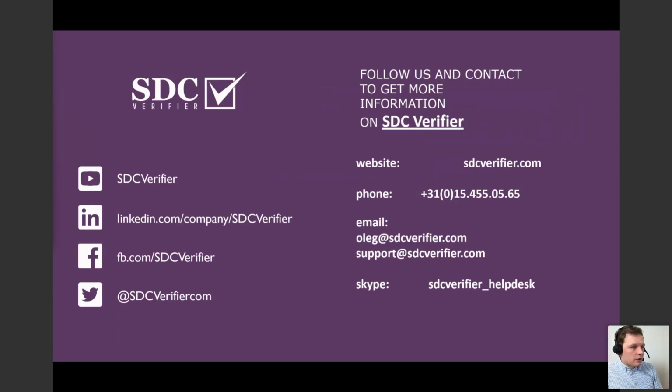The question is, can we do bolt calculation in SDC Verifier? Yes, you can. We can do AISC bolt check. We can do Eurocode bolt check. We have VDI 2230, where your connected plates are modeled as 2D elements or 3D elements, and you have all of your bolts modeled as a 1D element in between.